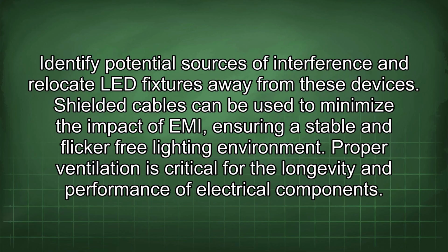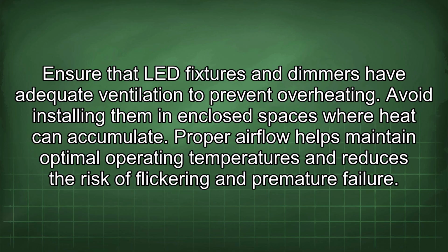Proper ventilation is critical for the longevity and performance of electrical components. Ensure that LED fixtures and dimmers have adequate ventilation to prevent overheating. Avoid installing them in enclosed spaces where heat can accumulate. Proper airflow helps maintain optimal operating temperatures and reduces the risk of flickering and premature failure.